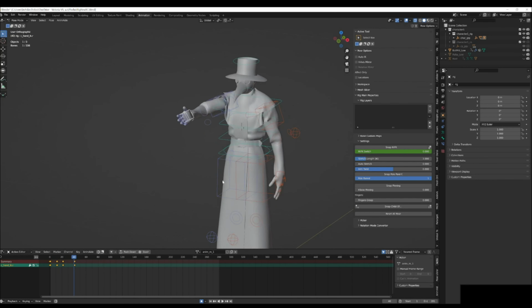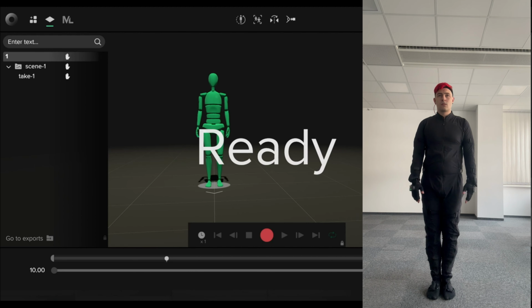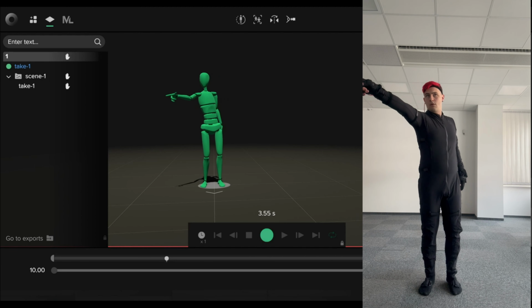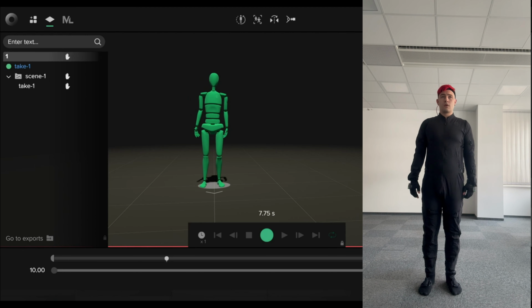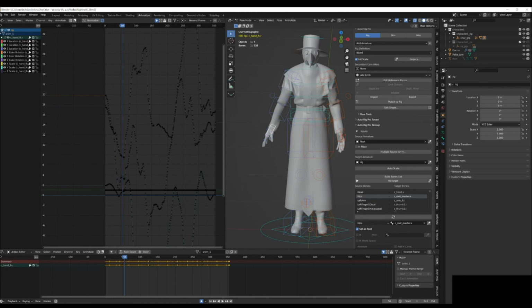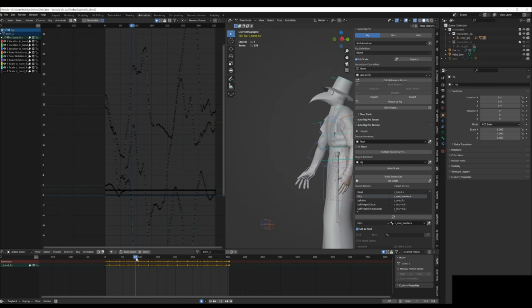Now we will create a similar animation using motion capture. I used a costume from Rokoko. To record movement, I use the Rokoko Legacy program, then from it you can export the recorded animation to FBX with different types of skeletons such as Mixamo, Rokoko, Maya, etc. In my case, I select a Rokoko skeleton and then retarget it in Blender to an Unreal skeleton.